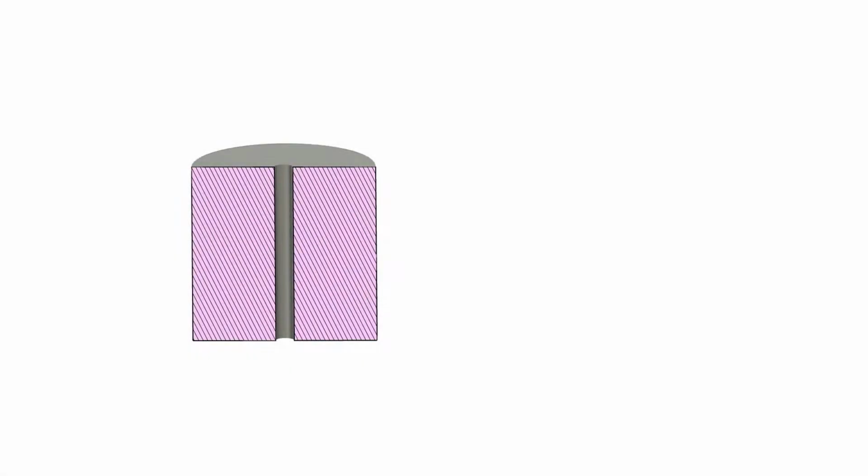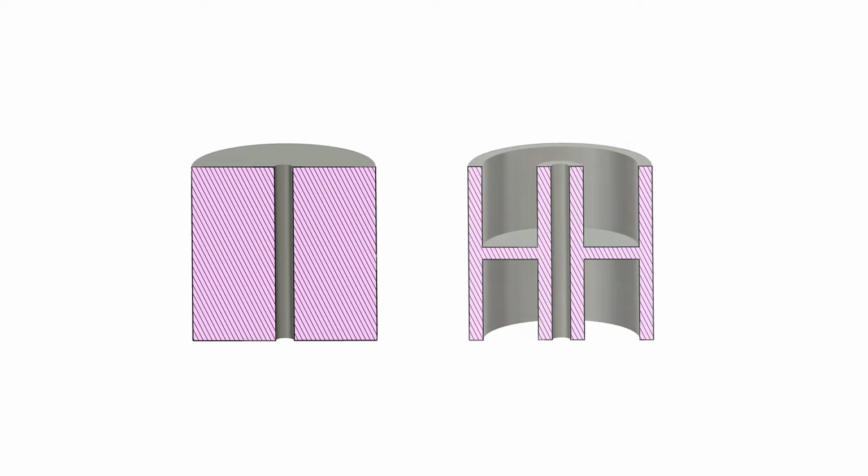The first consideration in injection molding is the part design. To shorten the cycle time, improve dimensional stability, and eliminate surface defects, a good guideline is to design your part so wall thickness is as thin and uniform as possible. The use of ribs is an effective way to achieve rigidity and strength while avoiding heavy cross-sectional thickness.